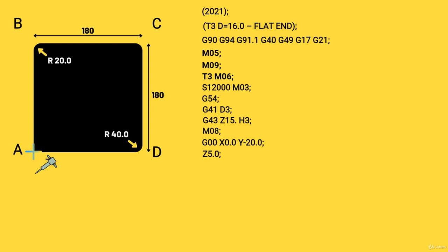Now as we move to cut around, our rapid travel command G00 is still at its tool change height. We are going to rapid it down to 5 mm above the job. Now using G01 with a Z depth of -5 mm, we will take the cutter 5 mm deep into the material. Let's assume it's 5 mm thick material, so this would take us right the way through the material.